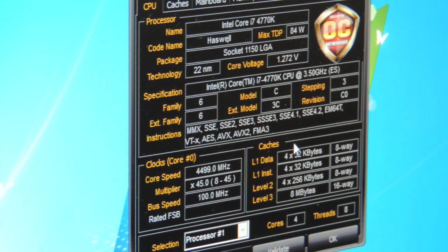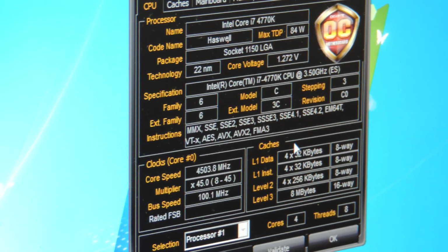So there's also a gear button. So I'm going to engage gear right now. And gear allows me to change the base clock in more fine increments. So I'm going to press plus and it should go to 100.1, 0.2. So it goes up between 0.1, 0.3 megahertz. So I'm going to press it one more time. There I go, 0.3. One more time. Should go to 0.6 now, really slowly. Okay. So yeah, it's more coarse. I'm going to go back down to 100. Press it a few times.